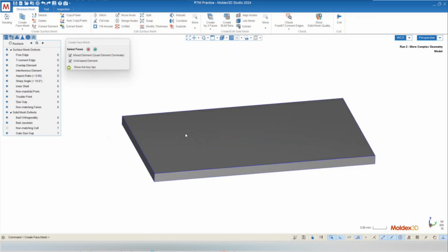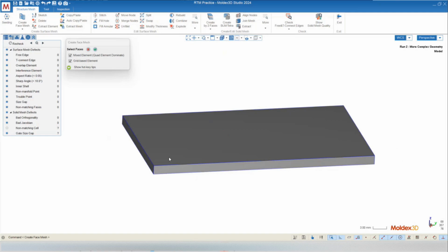But like I said, as far as the solver is concerned, the fact that we have a perfectly regular array of elements through the thickness is the most important thing. And so whether you have a triangular mesh array or a quadrilateral mesh array, the solver will be okay with either of them. Just the quadrilateral mesh array will be more efficient.